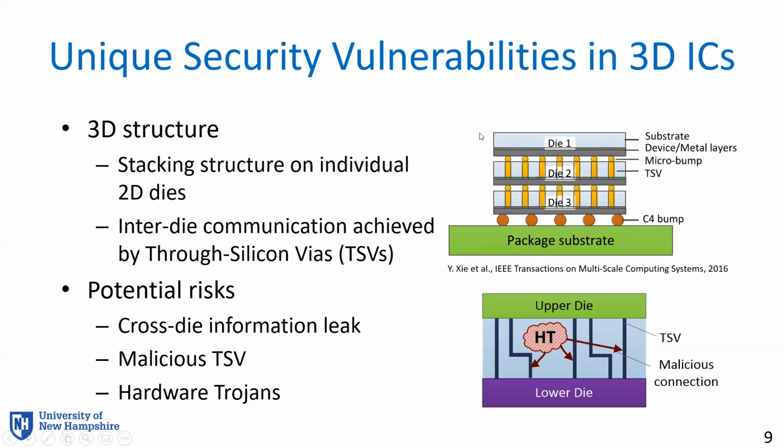Unfortunately, testing for 3D circuits is not that mature yet. For example, when you have a limited number of probes, it is not realistic to check every single vertical connection channel at the same time. Plus, with much smaller dies and smaller feature sizes for each 2D die, the probes we have currently could change the integrity of the TSV, for example, after testing. So there is limited testing ability available for us to perform very comprehensive testing on 3D systems.